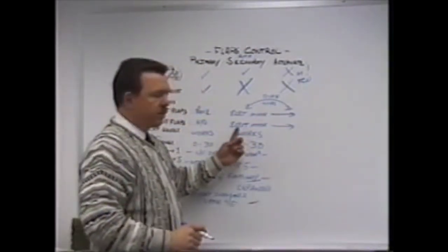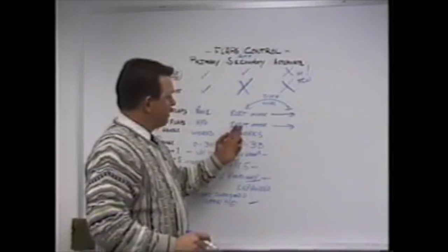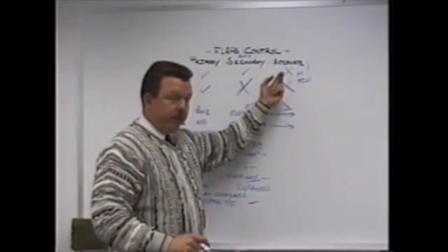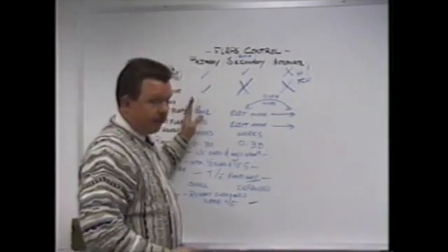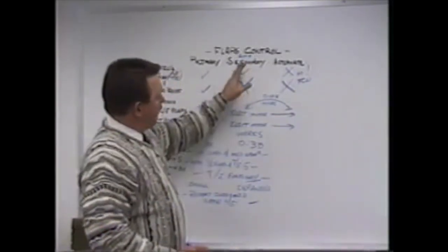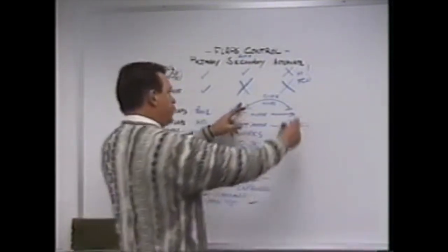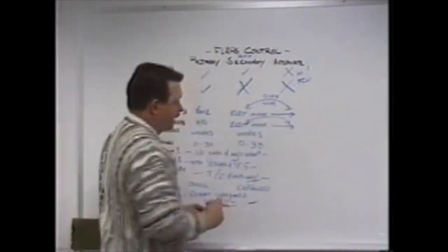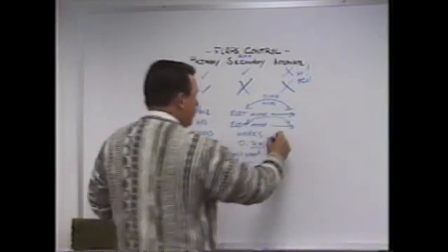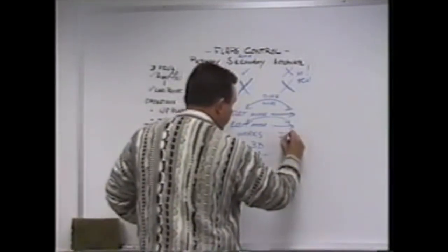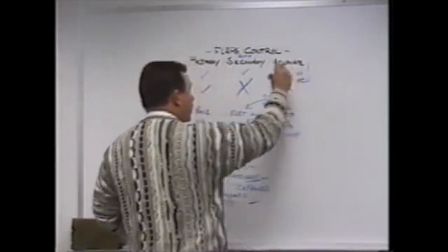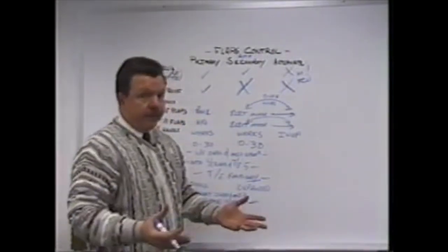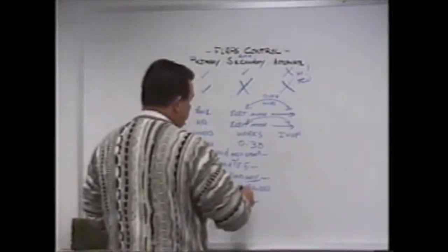So if your electric motor is giving you problems, you're not going to be able to deploy the affected flaps in either the secondary or alternate mode, but then the primary should have drove it out fine. If it's a control mechanism, then the electric motor should work, because we're going to use different wiring in either case. It's going to be different wiring with the same motor. The flap panel does not work in the alternate mode. So if I arm that alternate flap arming switch, the flap panel is dead. You can move it all around, nothing's going to happen.